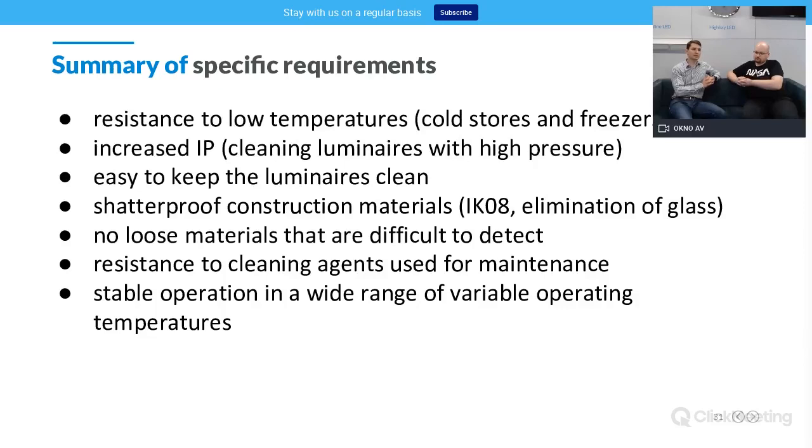And remember that for cold rooms, freezers, and so on, you can really save a lot of energy for the client because of the lower heat dissipation of LED technology instead of metal halides, for example. So this is really 15 to 20% of energy saving, and the cooling system actually requires much more energy than the lighting system. So that's additional savings for your clients. Please remember to include it in your savings calculators for your clients.